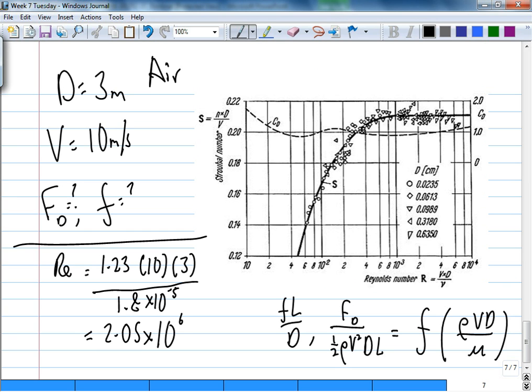The other thing to note, this Reynolds number, the range is very big. It goes from orders of tens to hundreds to millions to 10 million to 100 million. If you were to plot it on a normal linear graph, it's very painful. You can see the small part all shrink together and the big part all dominating. So to make things look easier, you can plot on a log scale. So here, you can see the log scale. And later, a lot of our graphs will be plotted in log scale because the range is just too big.